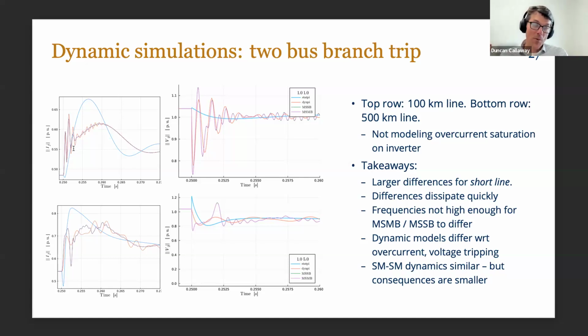So what we see here is, well, okay, we're getting some things that are perhaps not surprising. That is, some faster dynamics in both current and voltage occur that we excite on those dynamic line models versus the algebraic case. But we're also seeing some phenomena, like a large voltage dip, albeit on a very fast timescale, that comes from the dynamic line model and is not captured in the static pi model,